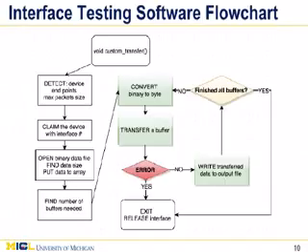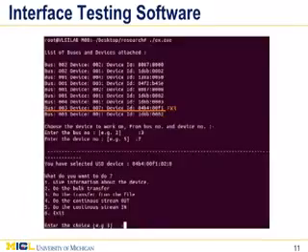Here's an illustration of the testing software. Underlying bus and device correspond to FX3. Then endpoints determine the direction of the transfer between FPGA and FX3. FX3 determines maximum packet size, and after its transfer and verification, it displays data transferred. From this interface testing via FPGA prototyping, we verify the ASIC interface with FX3 and USB-C. All signals are verified through both the interface program and ChipScope.